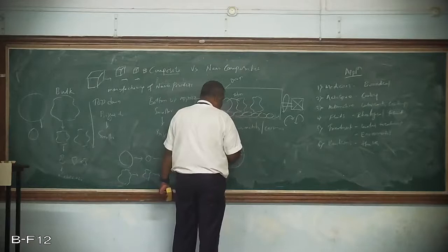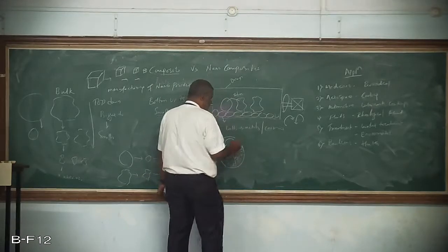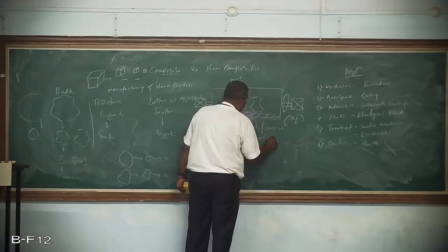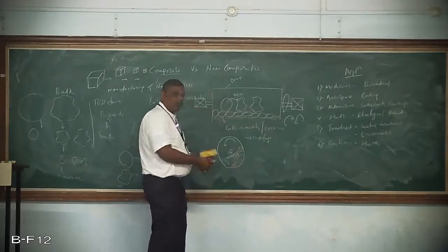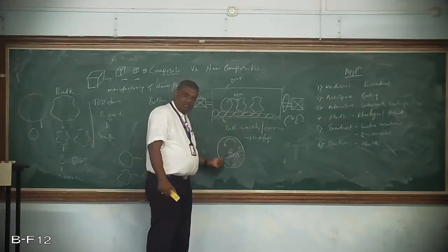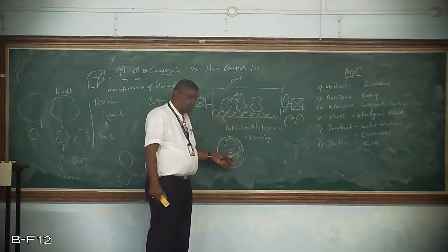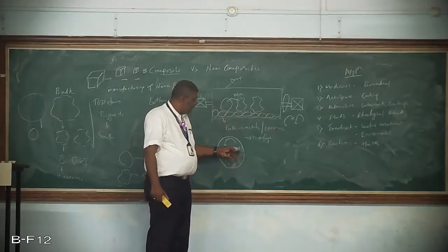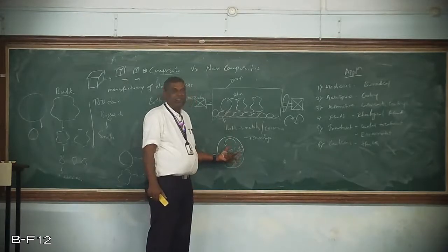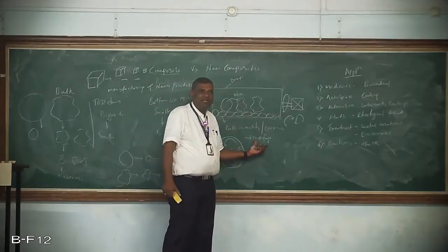So if the speed is more, then what will happen? You get a centrifuge. This centrifuge is nothing but there will be no breaking of the particles. The entire thing moves simultaneously, and there is no production of powder. Raw material and balls both rotate at the same speed. Okay, so there is no variation of the speed, and because of this there is no impact. So that particular thing is called a centrifuge.